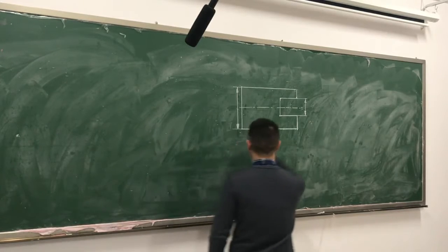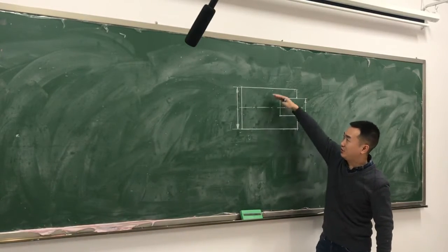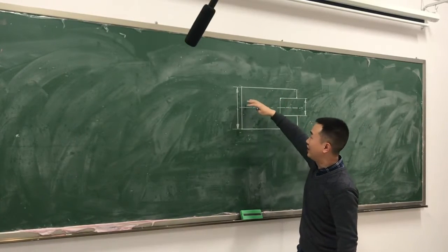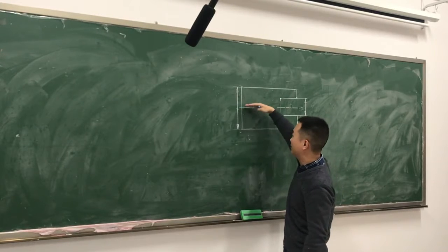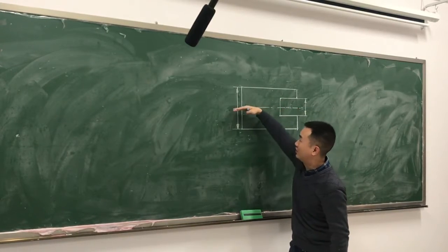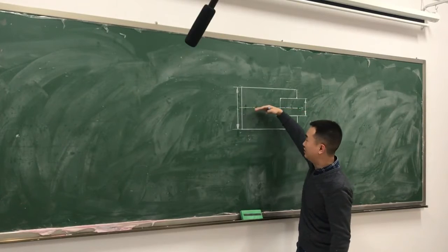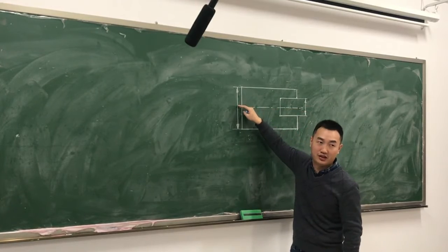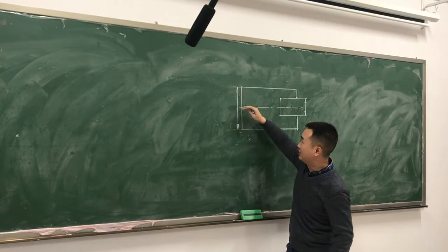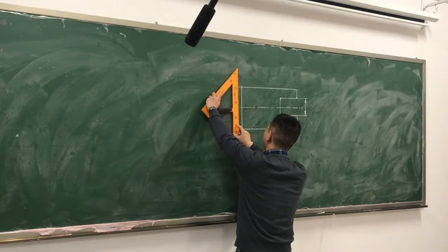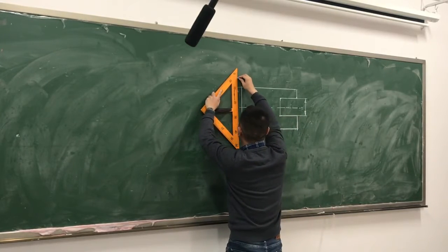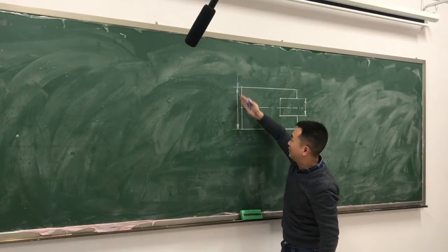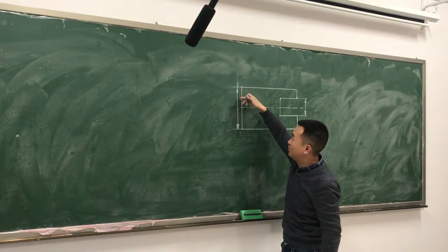So the median plane is here, right? Because this workpiece is symmetric, the lead line should point to the median plane here. So how do we indicate this is the median plane? We should add this dimension line here. The lead line should serve as the extension of the dimension line.